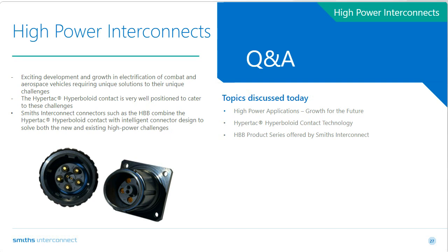On the 5 pole, you mentioned that each contact handles 60 amps. Does that mean it is rated to 300 amps overall, or is it derated when all the contacts are loaded? Great question. John, do you want to handle that? Yes. All contacts are rated 60 amps. They can all carry that current simultaneously. Where you would have to be a little more careful would be in a cable harness, where your cable type would become a factor. But in terms of the connector, it can handle the full maximum rated current as specified.